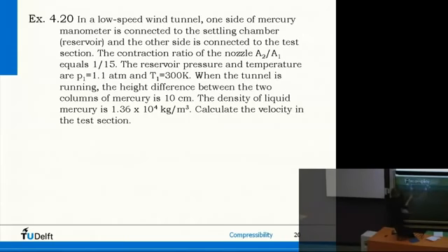Then if these pressures are not the same, with mercury here, we will get a difference in height, right? Because on both sides we have pressures pushing, so we have a force. The force is P1 times A. Here we have P2 times A. If they're not equal, then thinking about the balance at this location, the total force here is P2 times A plus the force from the mercury column.